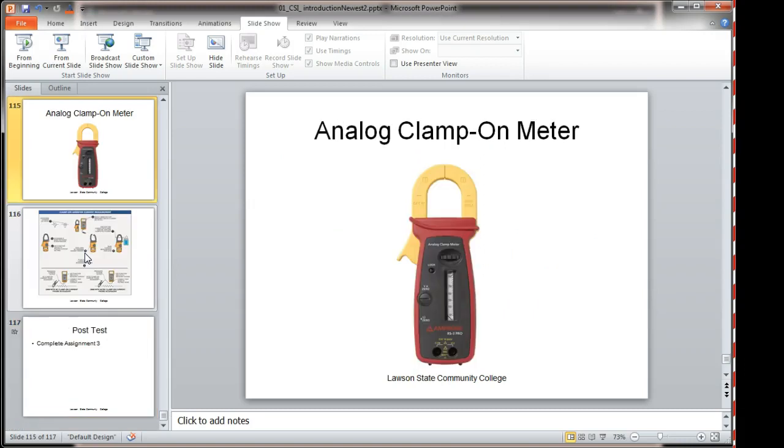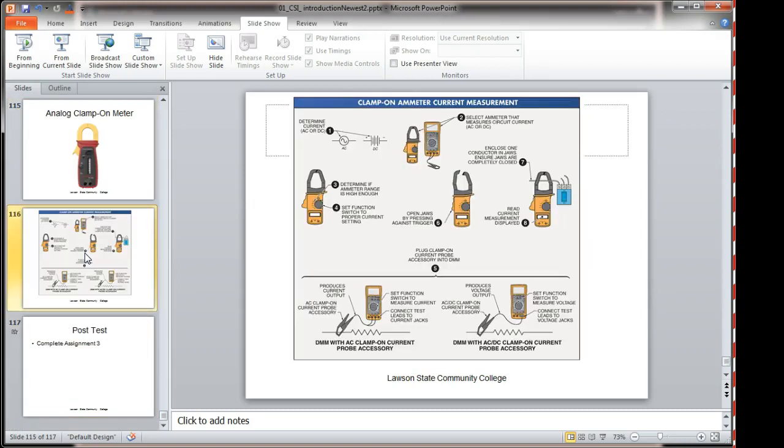This is a clamp-on, an analog clamp-on amp meter. What's nice about this is we can just put the clamps across an AC circuit. Most of them are rated at like 40 amps and 400 amps. If you're going to measure milliamps, you can't do it with a clamp-on amp meter because it takes a lot of magnetic energy to work those things. I need to look up the specs on these. This is a Fluke. It wouldn't surprise me if it had a Hall effect sensor so it could actually measure DC current, but I'm not sure.